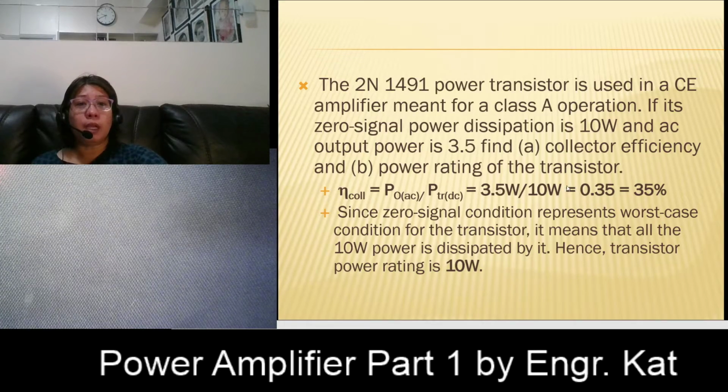So therefore, the collector power rating must be 10 watts because at zero signal power, it will experience a heat or a power contribution of 10 watts. So therefore, the type of transistor that you are using must have a power rating of at least 10 watts.